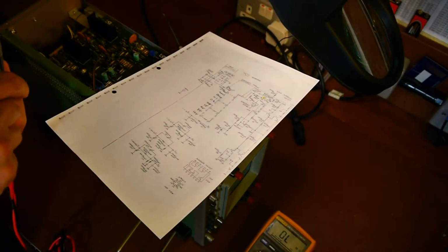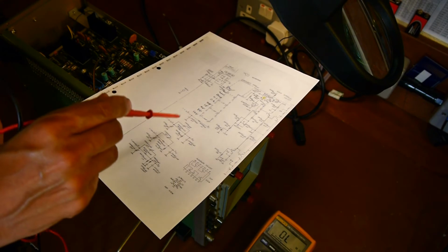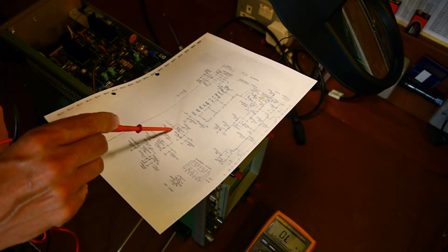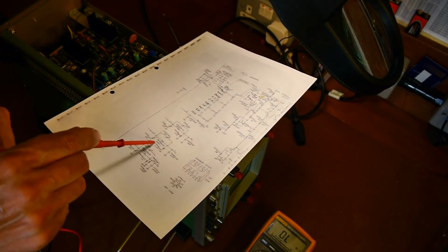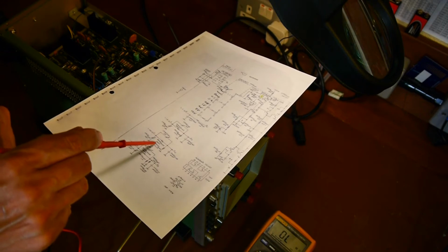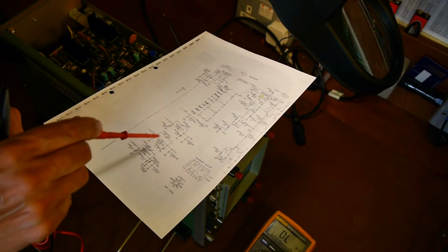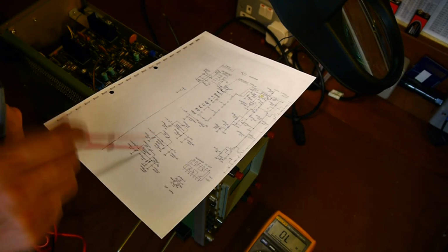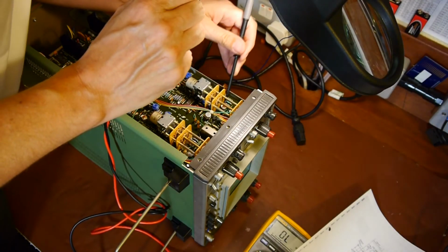And we'll just see if the values of the resistors are anything like what it says on the data sheet. So the first one we're going to check is, I think it's 900 ohm, sorry, wrong one, the 990k resistor. We'll check the channel 1 resistor and we'll also check channel 2. Remember, it's channel 2 that's got the fault. So where is it? There it is. Channel 1.